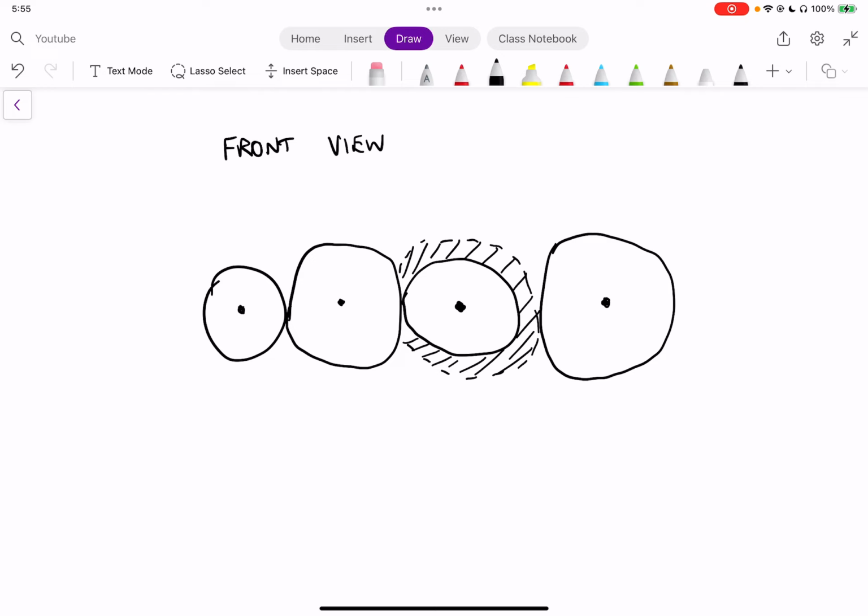Now, by convention, and this is how gear designers draw this essentially, they don't start with gear number 1. They actually start with gear number 2. So the first gear on the left side is sometimes a pinion, sometimes a gear, it depends. Usually it's a pinion. It is going to be called number 2. Then this would be number 3. This would be number 4. Then this would be number 5, which is on the same axis as number 4, but is side by side essentially. And then number 6.